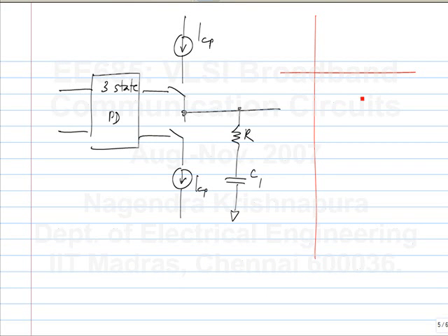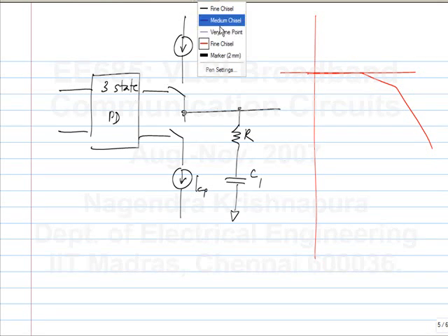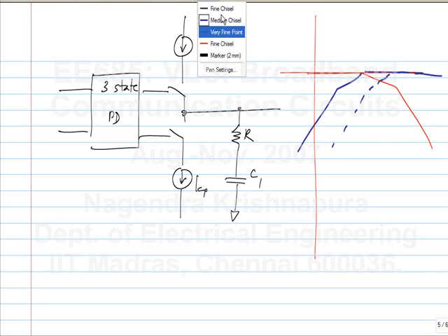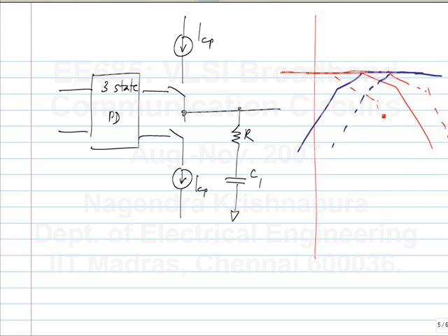From the reference to the output, it is low pass, and from the VCO to the output, it is high pass. Now if the VCO gives more noise, then you use this, and then the reference transfer function will move to this value. Okay. On the other hand, if the input has a lot of noise, you limit the bandwidth as much as possible, so that the transfer function from the input to the output removes a lot of the noise.